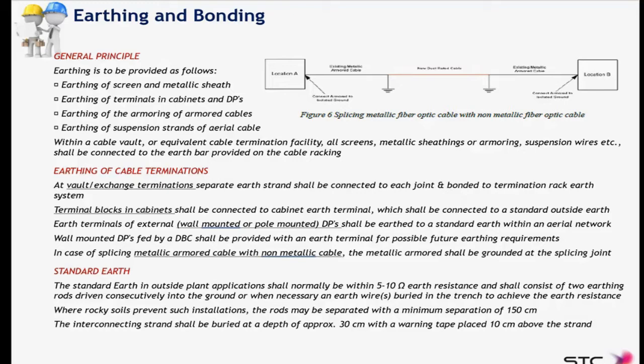In addition to that, we are going to detail some specifications about the minimum resistance of the grounding connectivity. What we are looking for is an earth resistance between 5 and 10 ohms. This is the acceptable value. How to achieve this? There are different procedures that you can follow as described down here, depending on the type of soil, sand or rock, or more or less difficulties in getting the expected earth resistance. We have to apply different technical solutions.